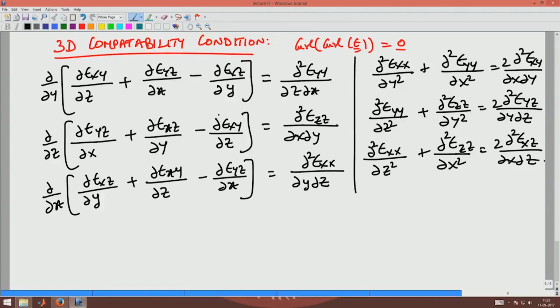Okay. Now, since strain is a symmetric tensor, you can write ε_xy is equal to ε_yx. So, I am not bothered about being precise about writing xy or yz or xz. Okay. So, either way you can write it, it is a symmetric tensor. It is for the same reason that when you look at the angle change between A and B, this will be 2 times A dot ε dot B divided by sine of θ_ref.